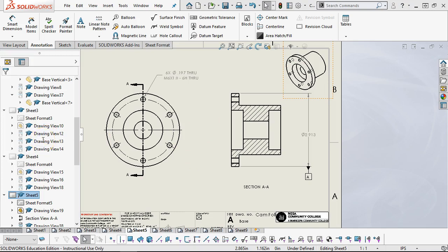All right, and then the minus, or would this be a plus? All right, so if we go minus 4/10, then if I was to go plus 5/10 of a thousandth, or half a thousandth, that would give me a range a little bit on the higher side. Or we could look back at the fit tolerances on the dimension. Since these are pretty much the same, the choice is to apply the dimension again or give it the 2 times. And then really the virtual condition of the datum is that central axis. So since we haven't added a center line, let's go ahead and pick up some geometry, and then I can pull these out.